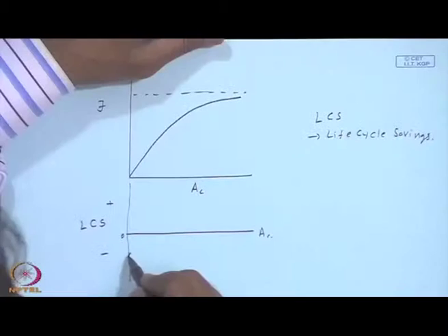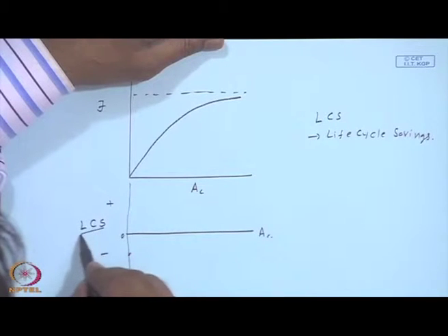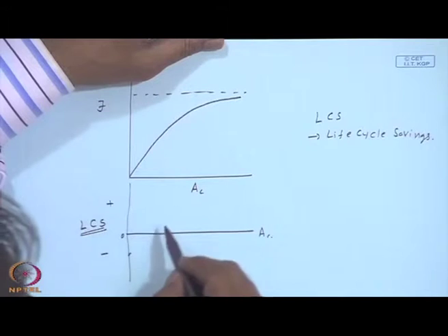One can take, depending upon the reality of the situation, the inflation in the oil price or the conventional fuel price, and the depreciation of the system, and the interest that you pay for the amount invested in initially installing the system. So, this is a complete economic exercise which will ultimately give you, if the collector system is going to operate for a period of 10 years, a net profit or net savings of so much. So, when the area is 0, but you have spent money on the other components, you will not have any life cycle savings, a negative life cycle savings only.